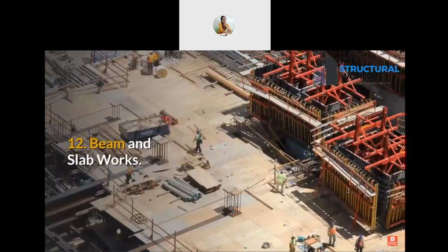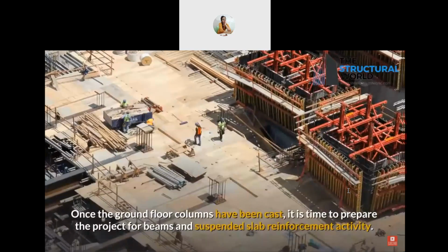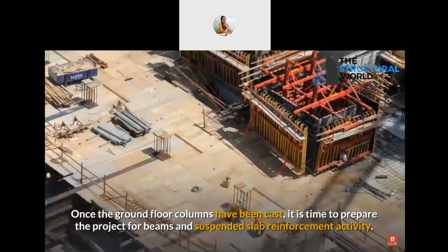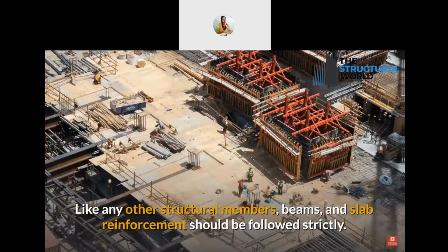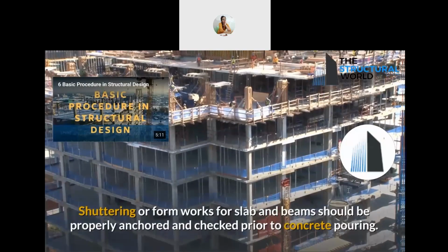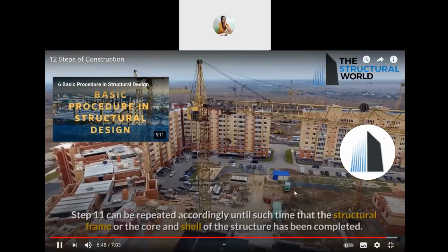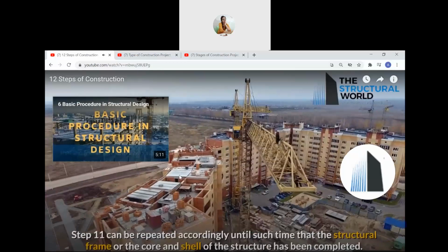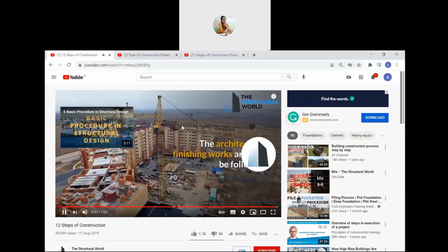12. Beam and slab works. Once the ground floor columns have been cast, it is time to prepare the project for beams and suspended slab reinforcement activity. Like any other structural members, beam and slab reinforcement should be followed strictly. Shuttering or formworks for slab and beams should be properly anchored and checked prior to concrete pouring. Step 11 can be repeated accordingly until such time that the structural frame, or the core and shell of the structure, has been completed. The architectural finishing works are then to follow.